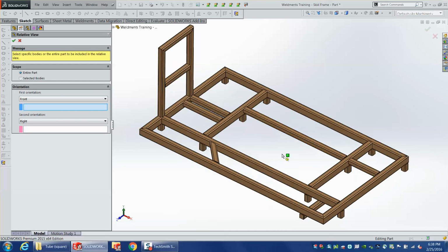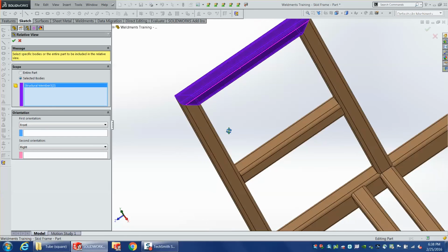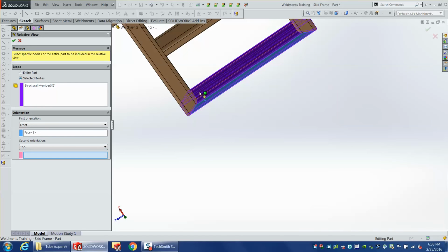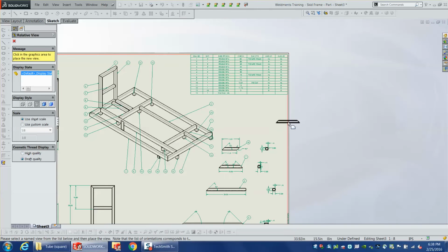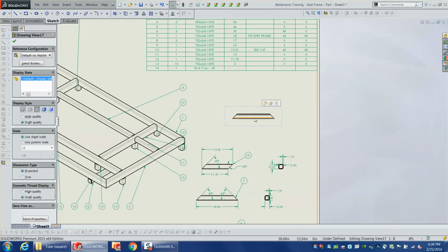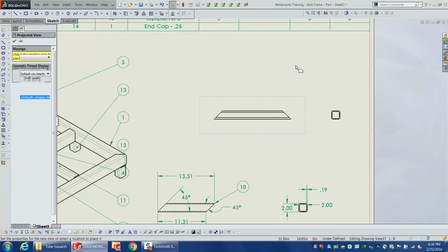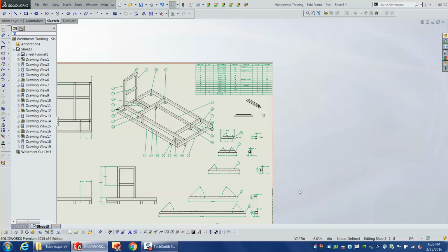And this is more powerful than a regular view where you select bodies because it lets me set up the orientation right as I'm choosing the piece. So if I want to create a view for this, I selected that body, then I can choose the orientation. Now I have a view I can project from it. And so this will update as I change my model.